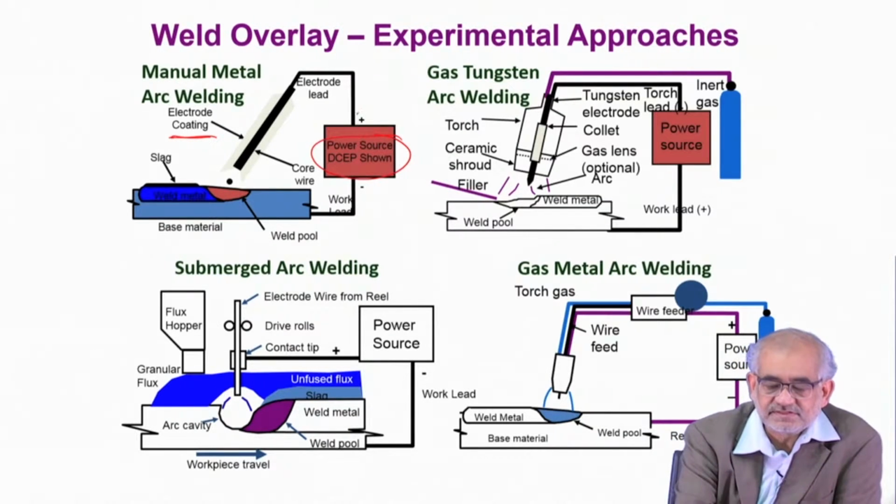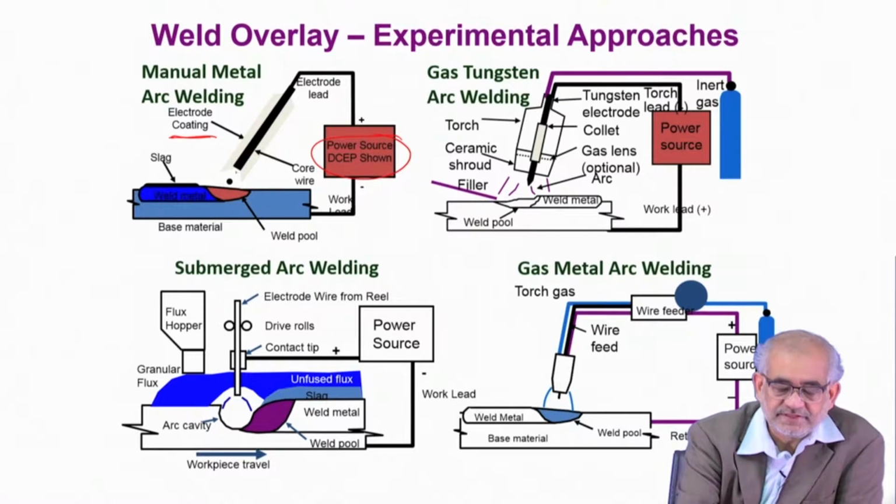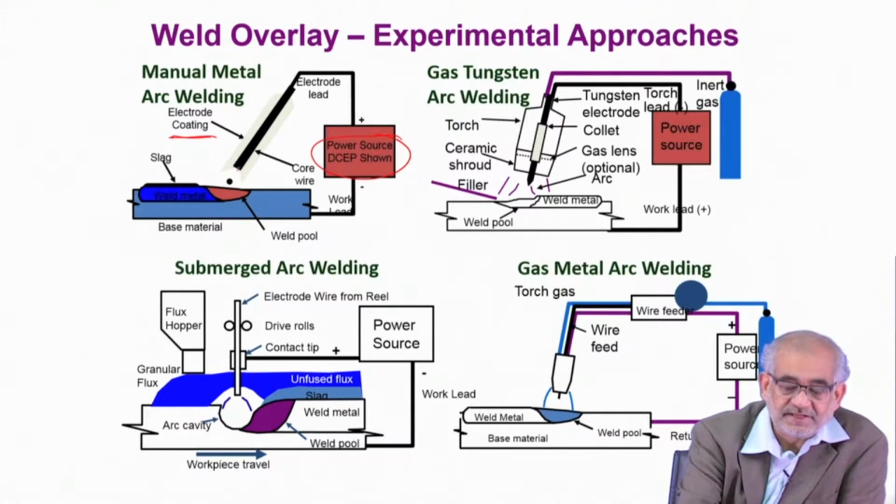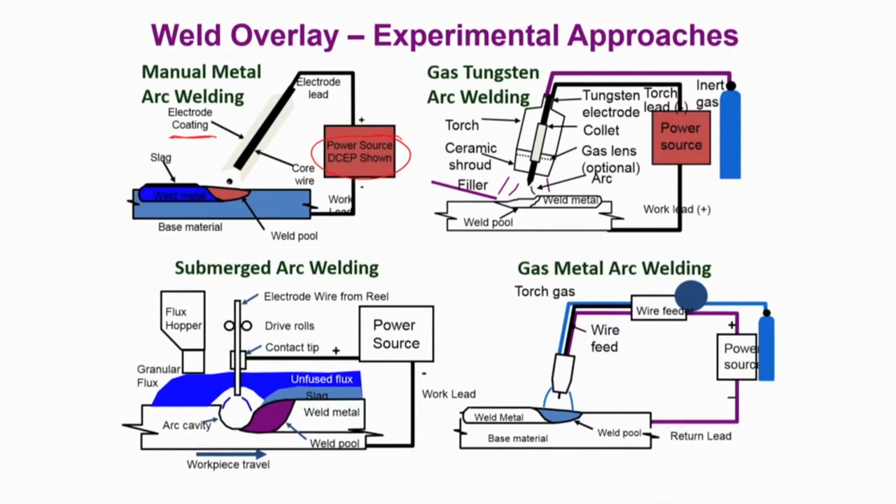Typically, you apply a very high voltage difference between these two ends, and as this electrode is brought very close to the negative electrode, an arc is formed. This arc is temporary, but depending upon the voltage applied, there will be a certain stability of the arc, and during the arcing process very high current flows in and immediately melts the metal.